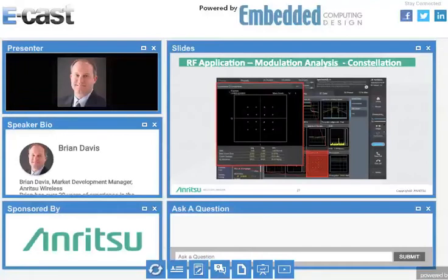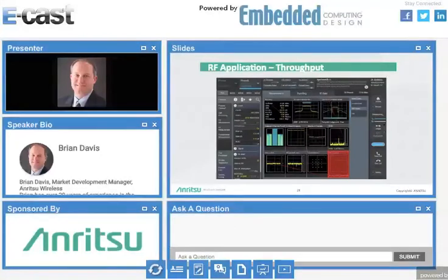And then of course constellation, this is a favorite of a lot of RF designers. It's the representation of the signal modulated by a digital modulation scheme. In this case, it looks like a 16 QAM signal there, and it'll show you the possible symbols that will be transmitted by the I and Q, the amplitude and phase. So you always want to have a nice tight point of I and Q there, not splatter all over the place. That'll give you a good indication of the performance of your transmitter.